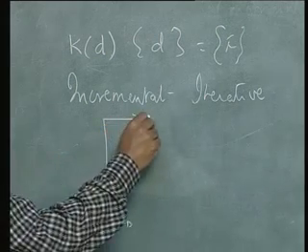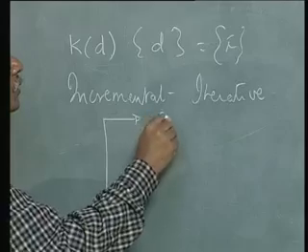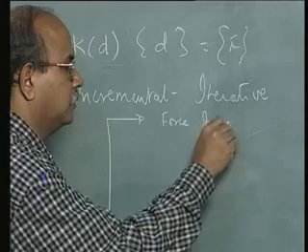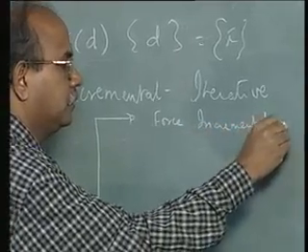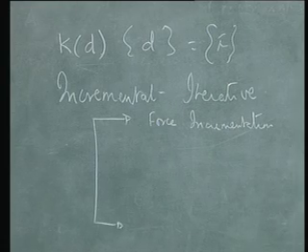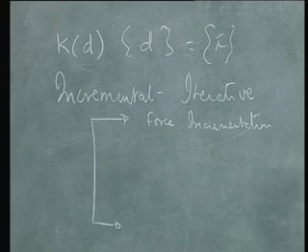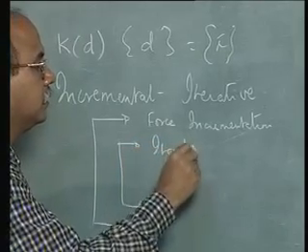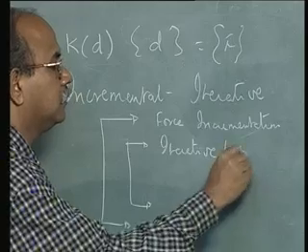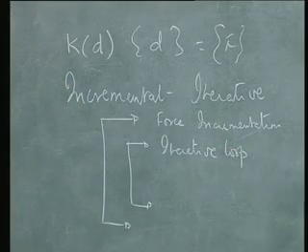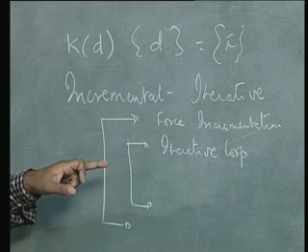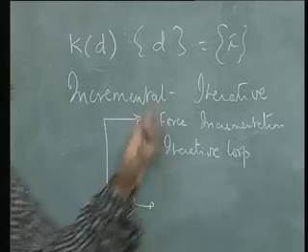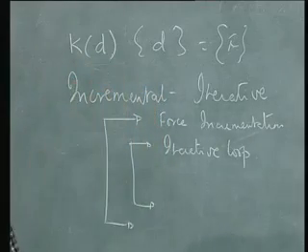One is that I will keep increasing the external forces, force incrementation, till we reach the final figure, and within this force incrementation I have an iterative loop, so that for the force given, I get the correct value of displacements, so that equilibrium is maintained.